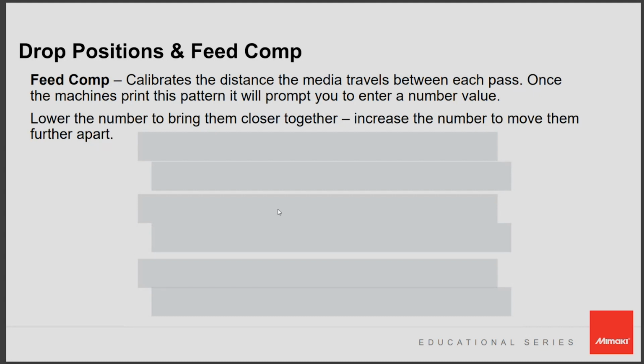You want to make sure that you're aligning that stepping as well, because say I wanted to print a true 4 foot by 8 foot board, but my feed comp is off and it's overlapping a little bit, it won't be 4 feet in the length. It'll be 3 feet, 11 inches and some change.